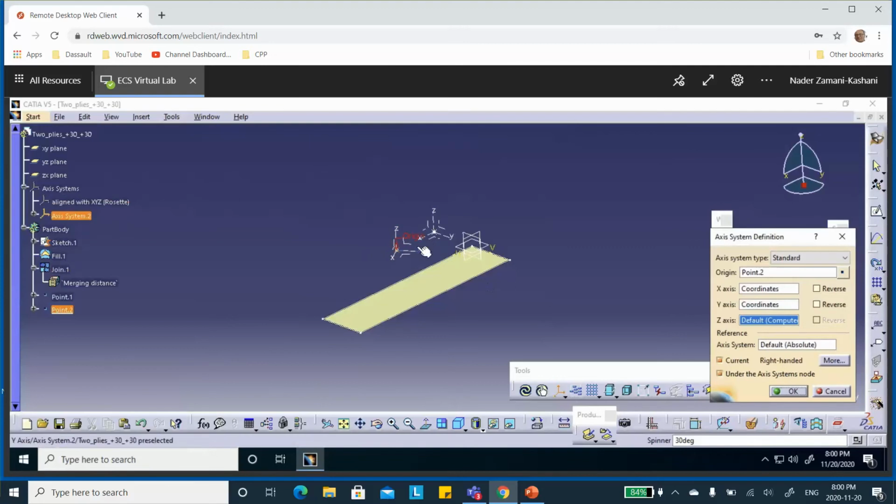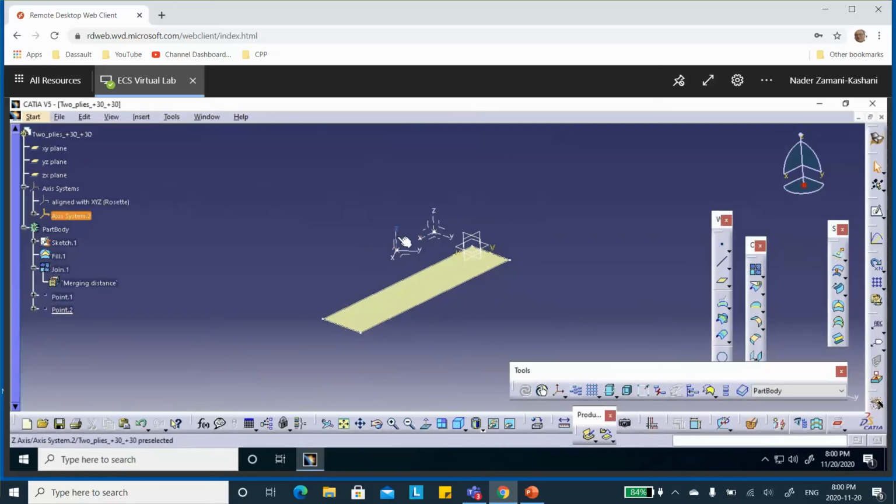See, it's rotated by 30 degrees because now X is going to be aligned with the fiber of these laminas. Okay, and I indicated why I want to create this coordinate system where X is aligned with the fiber direction: when you plot the stresses and things like that, for hand calculation purposes, we're going to compare it with the fiber direction, transverse direction, etc.